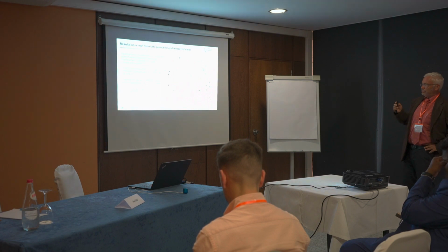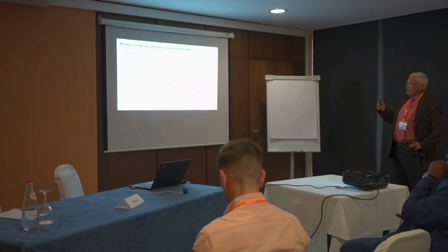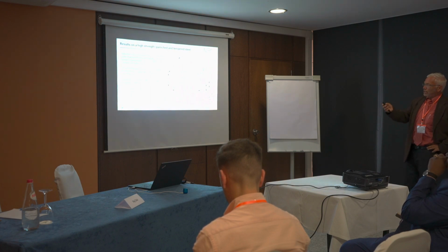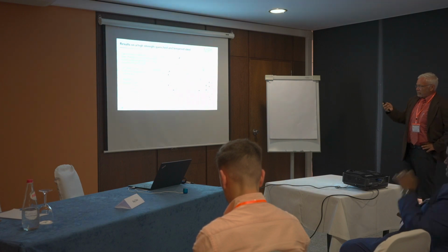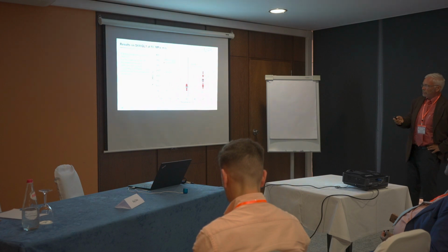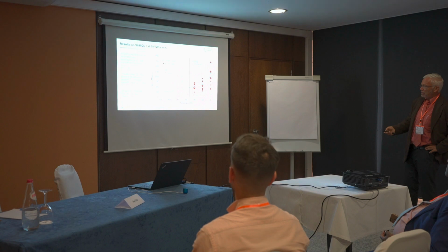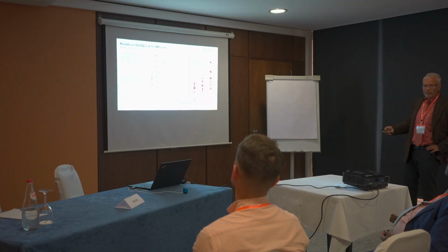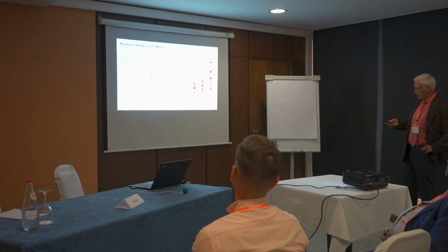And then we looked at whether there is an influence of the material, and this is the plate of the S690 high strength material. This is the position where we took the specimens from, and what you can see here for 10 to the third, it looks very different. And we have no influence even for 10 to the fourth. We only have influence if we go really far, and this is too far for the evaluation because there is this plus minus 50 degree validity criterion.